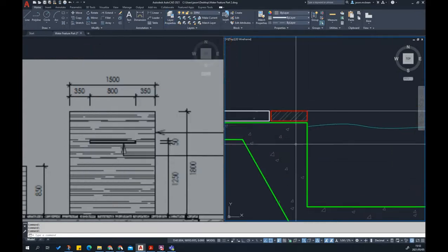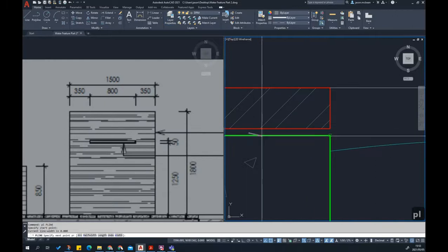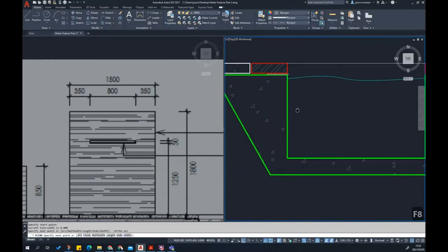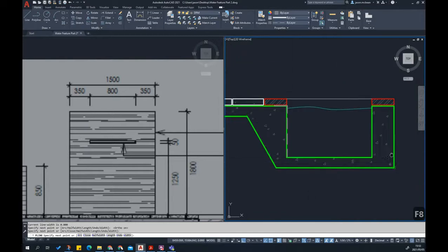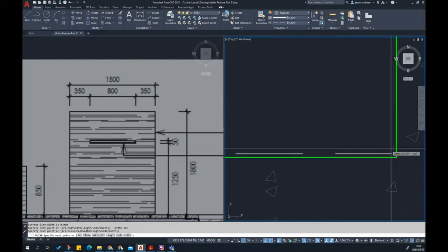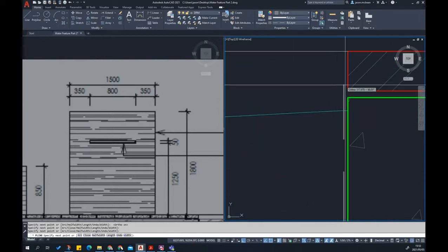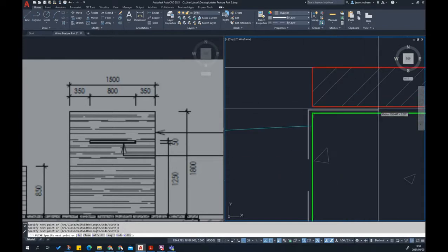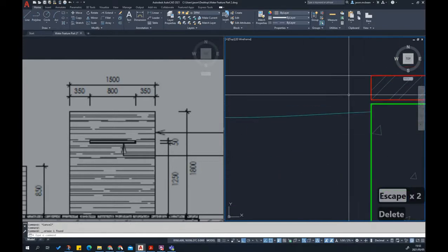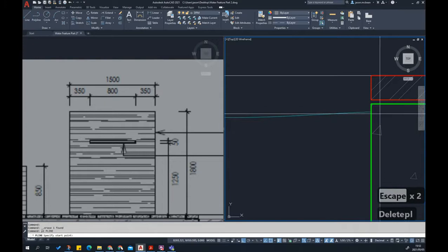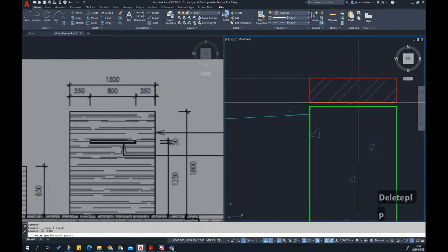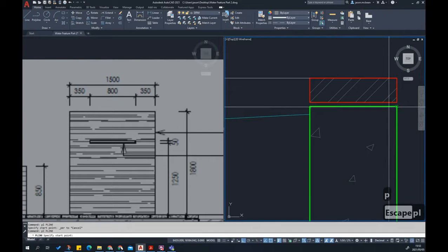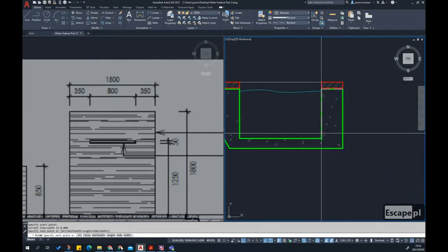And now I'm going to say polyline. For now, I'm just going to do this very roughly, F8, because I can use my stretch tool to bring it back as close as possible. So here I'm just tracing more or less. Or alternatively, what you could have done was go polyline, and work along this line over here. You just say polyline, and you follow this line work quickly.